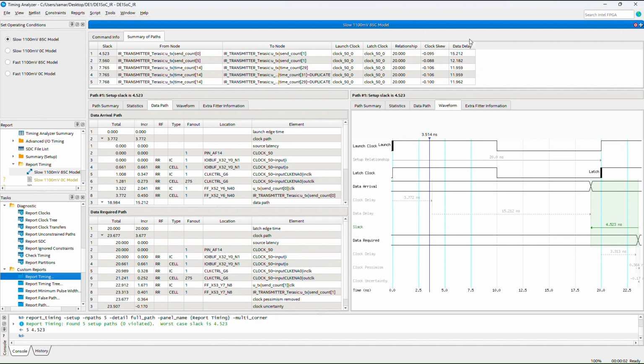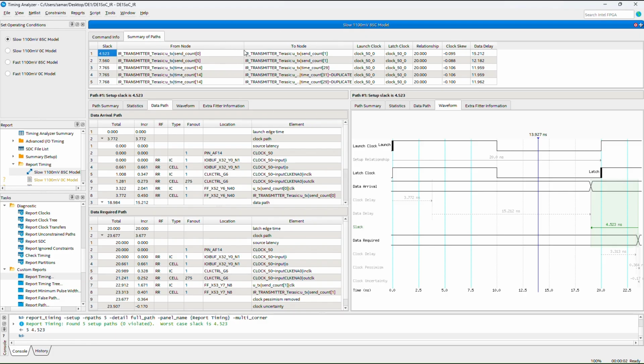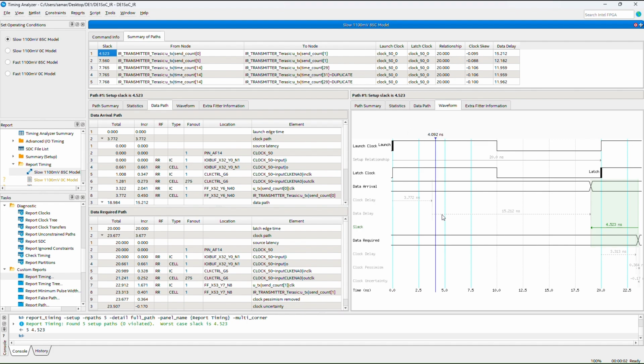As you can see, the delay has increased, which is expected because we basically moved 2 important blocks of our critical path to either corners of our FPGA. Because of that, we have a lot of data delay. So that shows that this chip planner gives you the flexibility to move the cells around so that you could create more optimized designs and fix it yourself. So yeah, this is the idea.